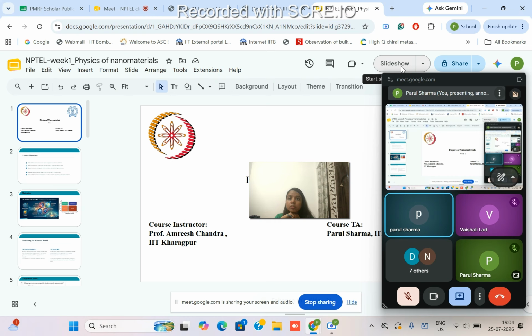Now, when we are dealing with the electrochemical double layer capacitor, what is happening here? We are using the porous substrate. Because of that porous structure, it will give a higher surface area, so that A will increase, and that will increase the electrostatic ion adsorption, which will allow us rapid charging and discharge cycles in seconds with higher energy density. So because of using nanomaterials, we can increase the storage powers in supercapacitors.